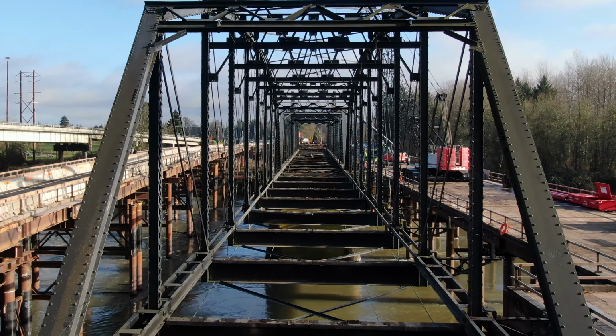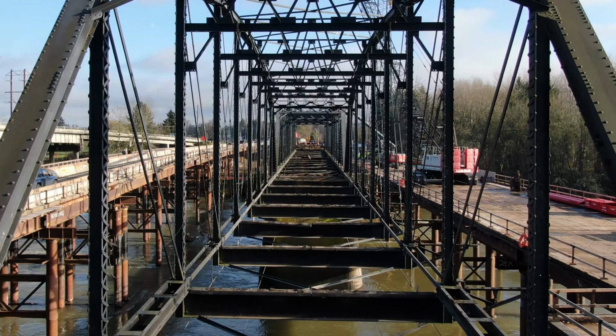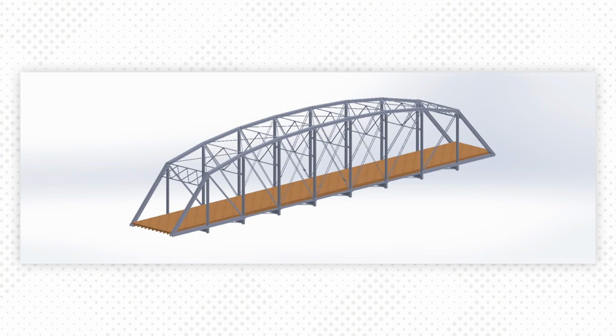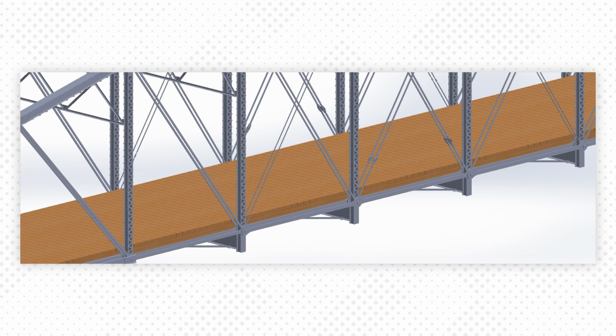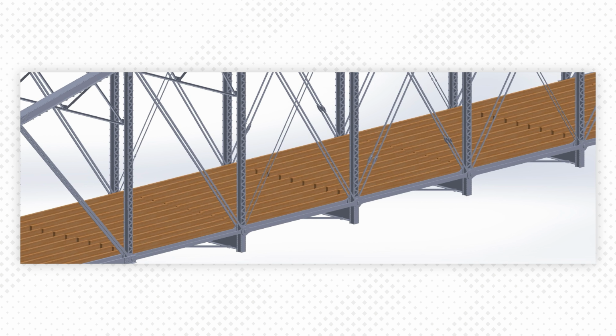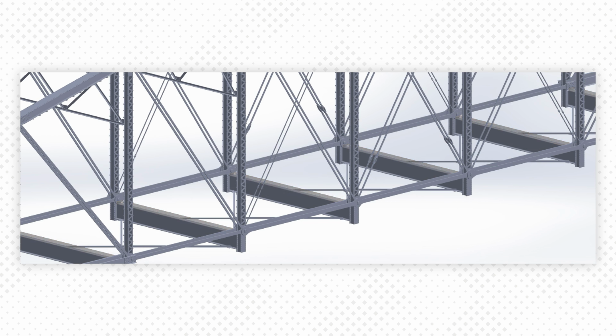Let's look at the beam that ties the 2 trusses together on the Van Buren Bridge. While the primary spans of the historic Van Buren Bridge are trusses, 3 beam-type framing members carry load from the vehicle wheels to the trusses. The timber deck, acting as a short beam, holds up the vehicles. The deck is supported by 19-foot timber stringers. These deliver their load to the steel floor beams, which are supported by the truss verticals.